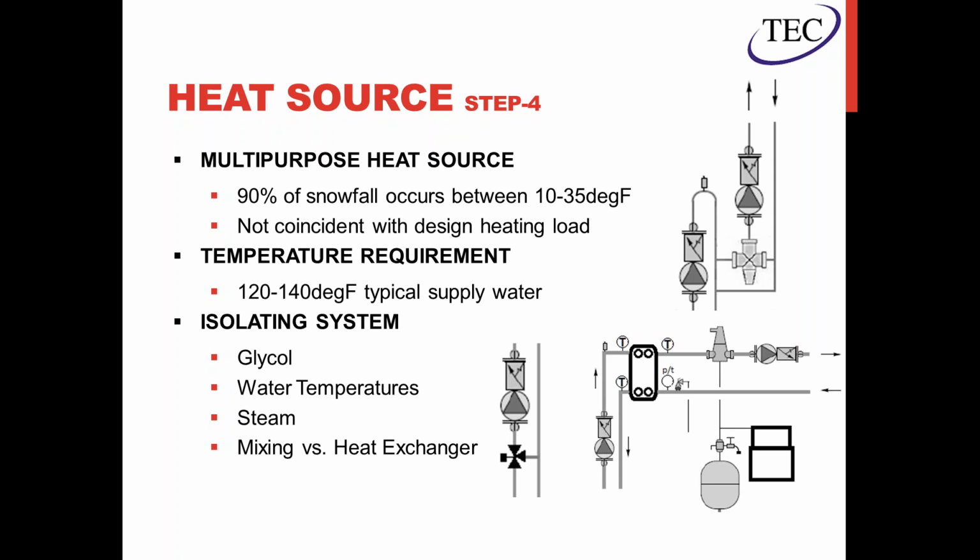So in addition to your typical boiler systems, you can use all sorts of different heating sources, as long as you can provide those water temps. They could be chiller tower water or heat recovery from a chiller itself, electric boilers, or heat exchangers, siphoning heat off of anything else you're trying to dump heat.